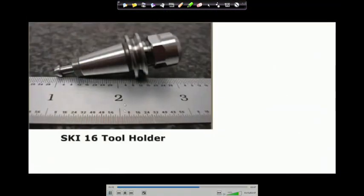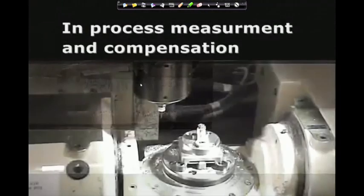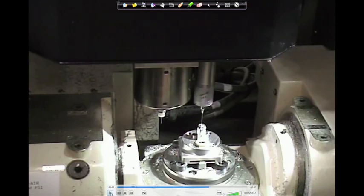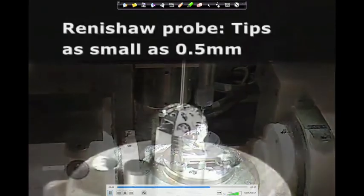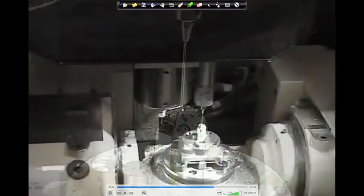So, once that is done, now this is the tool face interface. It is used for rotating at 7000 RPM, and now in-process measurement and compensation. This is the tool which is used for measurement of this particular component. The earlier one was used for measurement of the status of the cutting tool. It is laser guided. This particular tool will move into that location and the laser will confirm the edges and the length, and this is used for measurement of the cutting tool. This sensor will give you all the dimensions. It is moving in the other direction, in this direction, to find out the radius or the diameter of this part, and then it will move.